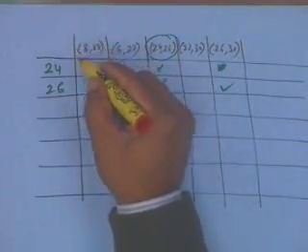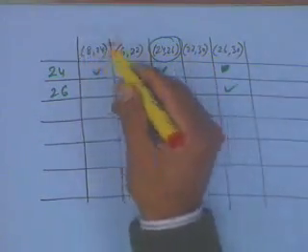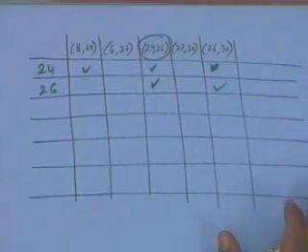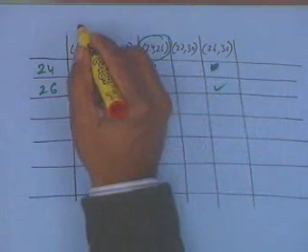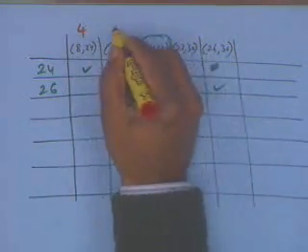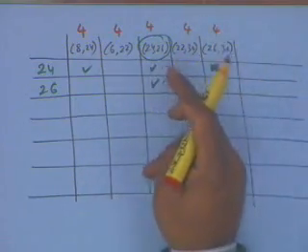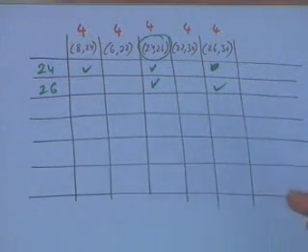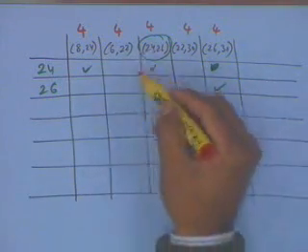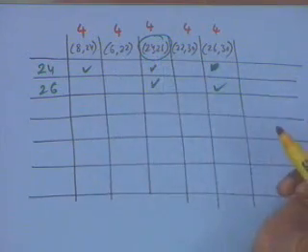There is a certain cost associated with this. What is the cost associated with this? With each of the prime implicants there is a cost. The cost is actually the number of literals that are present. The cost of a minterm is 5. The cost of this implicant is 4. Actually the cost of each one of these in this case happens to be 4. But they can be different if you have had other stages where you have eliminated 2 literals or 3 literals and so on, then the cost could be different. In this case the cost of all of them is 4.